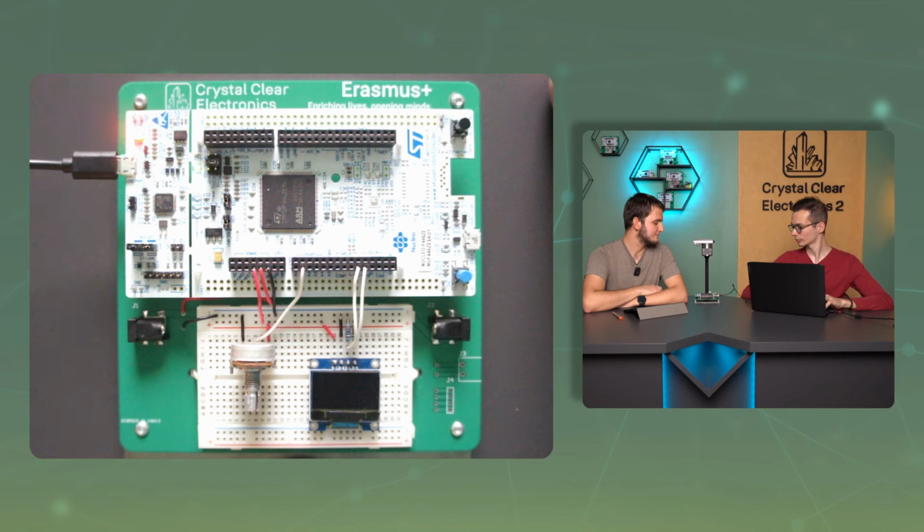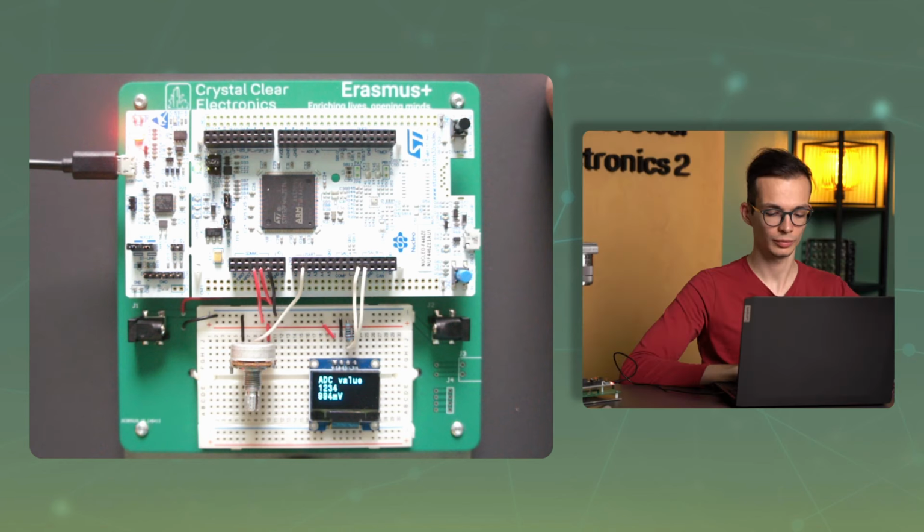I think we are ready to program our device. I've already compiled the project and I am starting to upload the code to the device. Let's see what we see when the programmer is done. Right now the programming is in progress, and it's done. If everything works, the display will show the ADC value on the top line of the small OLED display. Below that you will see a numeric value between 0 and 4095 and a value between 0 and 3300 mV.